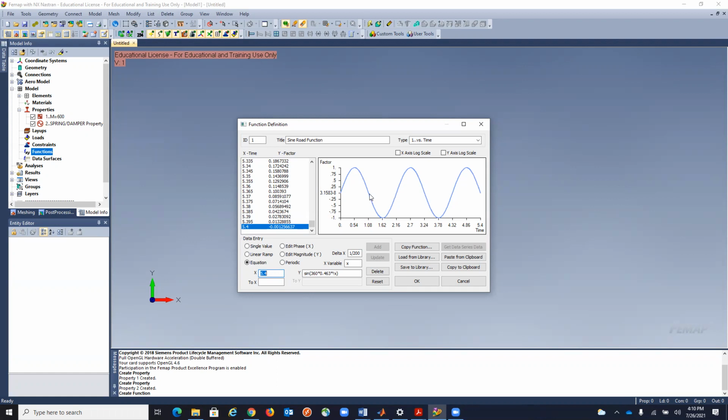Okay, 1 should be enough, but for the sake of showing that. So basically with that time step, I did some preliminary trial and error, and I found out that this was enough. Then this is something that I do every time. You don't have to do it, but sometimes it can help you not to create problems, to make sure the last value here is 0, so that we start from 0 and we finish in 0. You can change this one to 0, but generally what I do should not change anything.